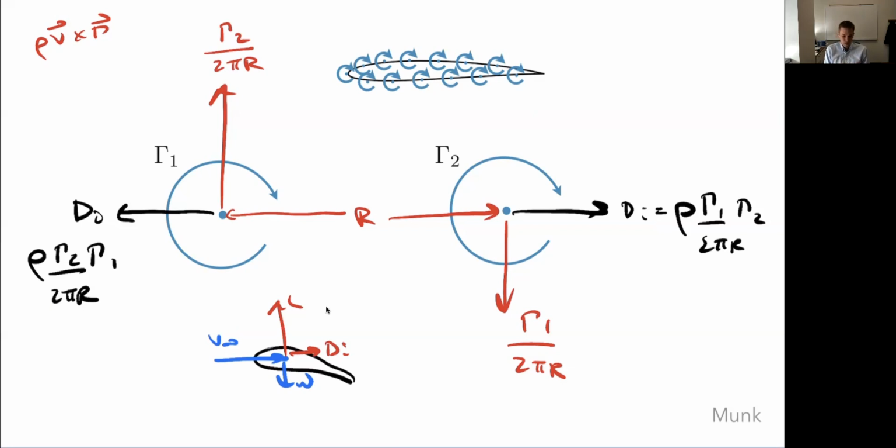All right, so we'll look next time at some numerical approaches, kind of like as we went from thin airfoil theory to a panel code, we'll kind of do the same thing. This lifting line theory, like thin airfoil theory, gave us some really useful analytic expressions that we could get from doing the integrals analytically. We got these formulas for induced drag. We got some insights into some approximate formulas for lift curve slope. Now we're going to go look at a numerical method, somewhat like the panel method we did for airfoils, but now we're going to be able to solve lift distributions and induced drag for wings.